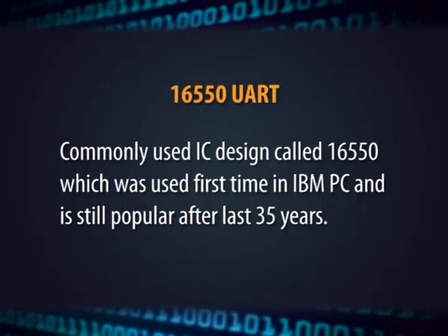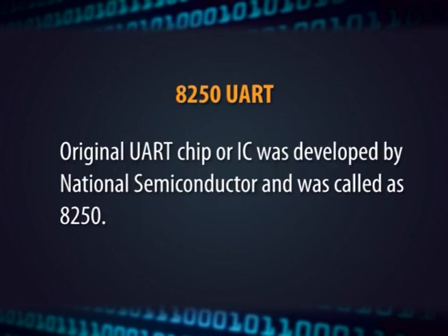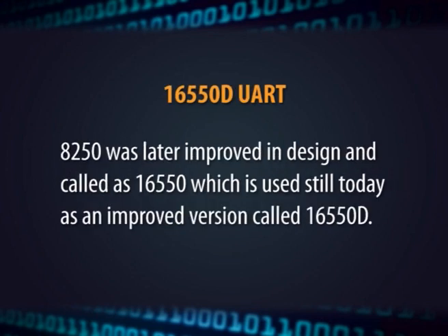UARTs have been designed by several manufacturers for several different microprocessors. We will focus on the most commonly used IC design, called 16550, which was used for the first time in the IBM PC and is still popular after the last 35 years. The original UART chip, or IC, was developed by National Semiconductor and was called the 8250. It was later improved in design and called the 16550, which is still used today as an improved version called